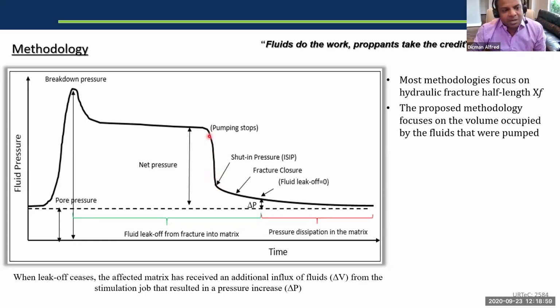Okay, even after we start pumping, the fluid still continues to leak off because you have created some pressure inside those fractures. It's going to leak off. And after a long time, we don't know, maybe 2 weeks or 3 weeks of an actual job, the fracture closes. Now, even after the fracture closes, you have some fluids sitting inside the pore space created by the proppants. It'll still leak off. It's sitting at a higher pressure.